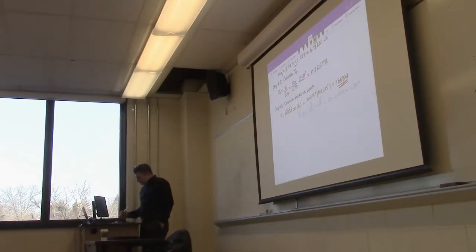Okay, so then moving on, Q is going to be equal to magnitude of V, magnitude of I, sine of theta V. So plugging in those values again, that will give us 1031 var.